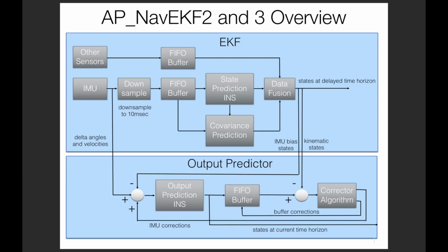So the comment is that if fusing in something with a separate positioning system that's got its own frame of reference, might be based on the landing pad, it's a different origin. We want to fuse that in parallel with the GPS data. Then you need to estimate the offset of the reference position, the origin of that source of data relative to the origin of the GPS data, and that would require additional states. So now we're up to 29.